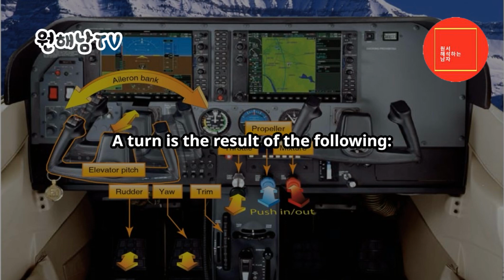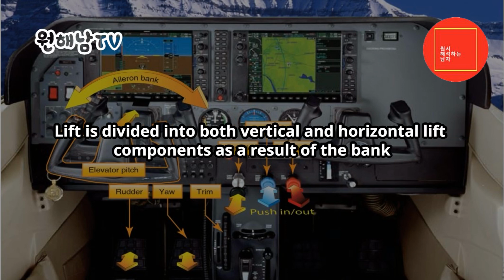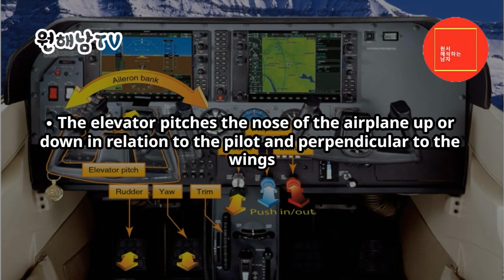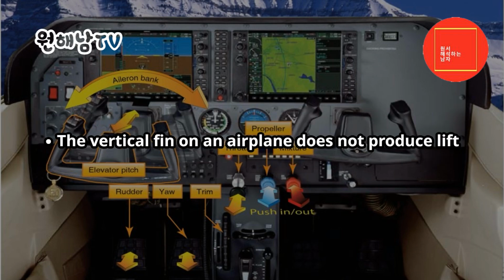A turn is the result of the following. The ailerons bank the wings and determine the rate of turn for a given airspeed. Lift is divided into both vertical and horizontal lift components as a result of the bank. The horizontal component of lift moves the airplane toward the bank direction. The elevator pitches the nose of the airplane up or down in relation to the pilot and perpendicular to the wings. If the pilot does not add power, and there is sufficient airspeed margin, the pilot needs to slightly increase the pitch to increase wing lift enough to replace the wing lift being diverted into turning force, so as to maintain the current altitude.